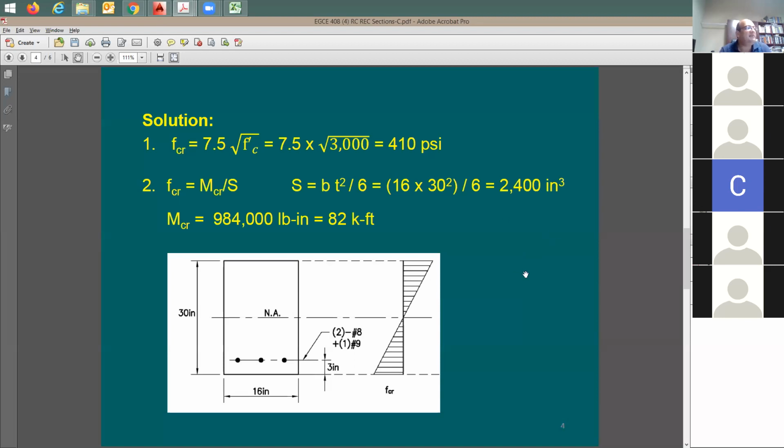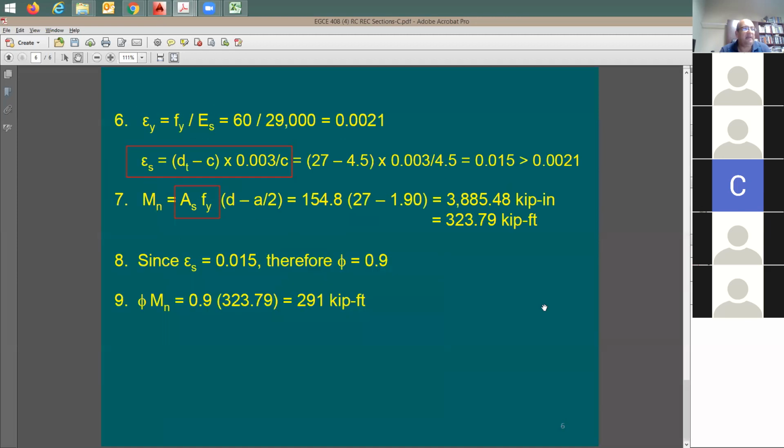Which means if I take this beam here, and you have a couple of rebars on the top, and you put them in the analysis that you haven't seen yet, because all that you have learned now is how to find out Mn for a rectangular section with only tension reinforcement. We're not talking here about a doubly reinforced beam, which means compression and tension. In this case, the compression reinforcing is going to be adding a little bit to this flexural capacity. I'm going to say maybe 10%. So it's not going to be much.